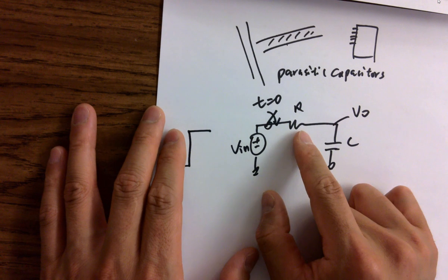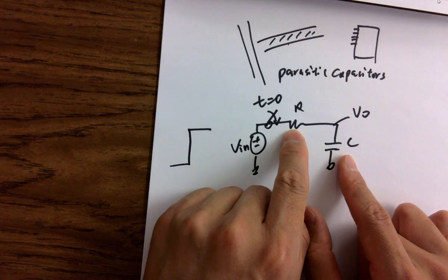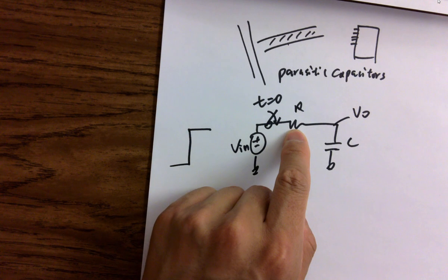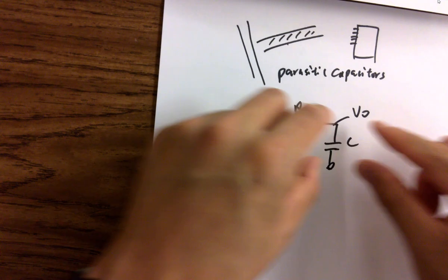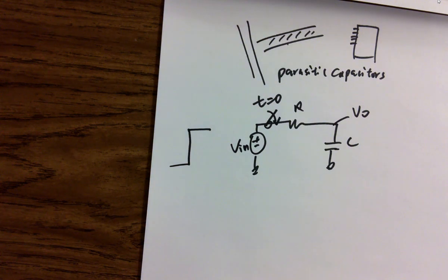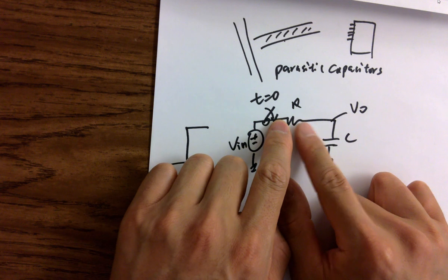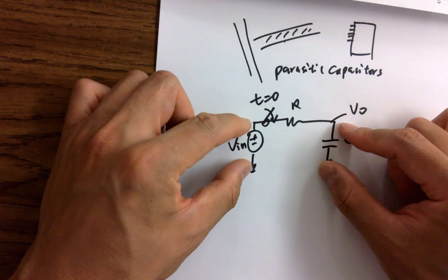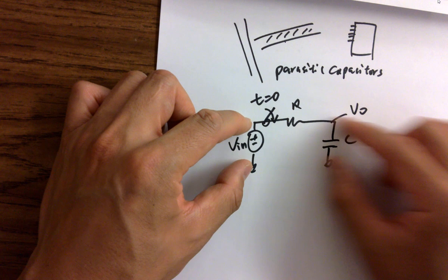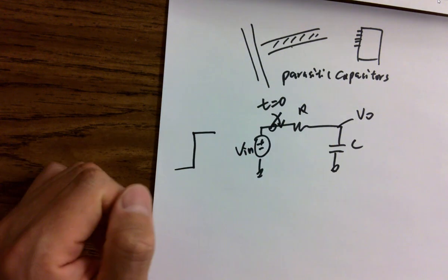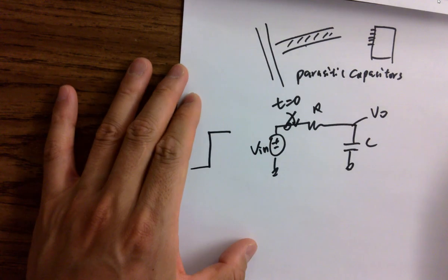But in the worst case, it's a huge resistor to limit the current, and you have a huge, ocean-sized cap, but you are using a straw to dump water into it. It takes thousands of years, but eventually it will be filled up. There won't be any current going through the resistor because they have the same voltage. Same voltage, no drop, no pressure going either to the left or right.